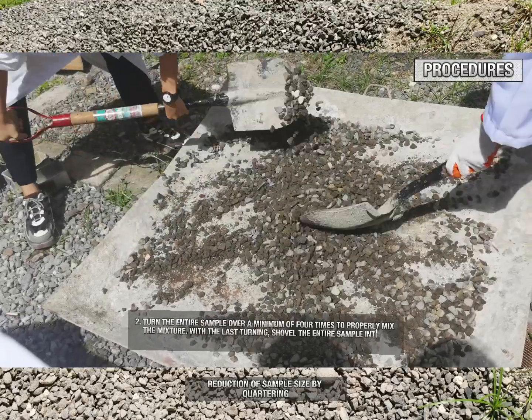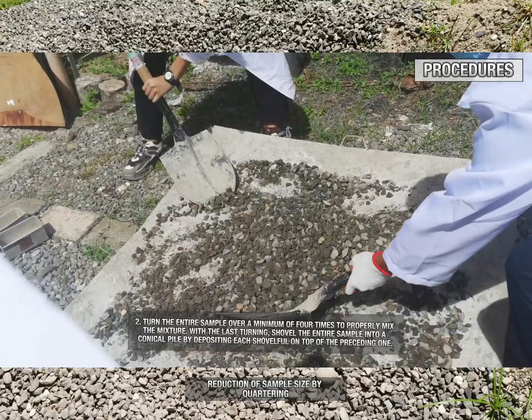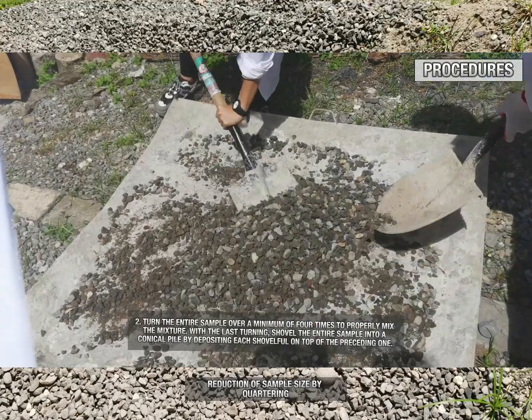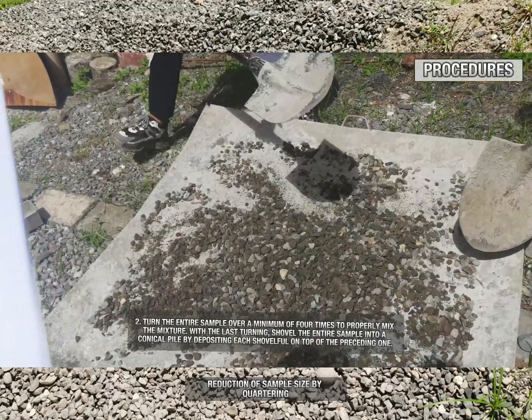Turn the entire sample over a minimum of 2 times to properly mix the mixture evenly. The last turning, shovel the entire sample into a conical pile by depositing each shovel on top of the preceding one.